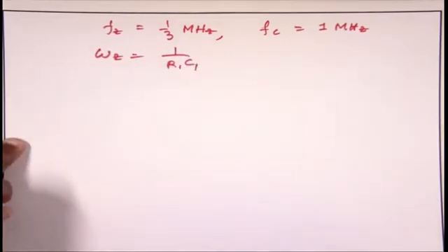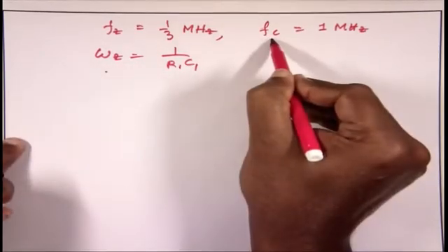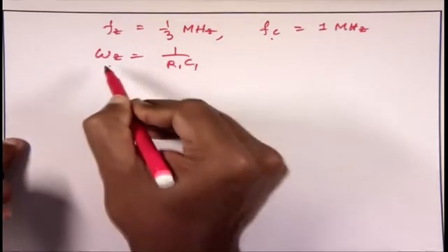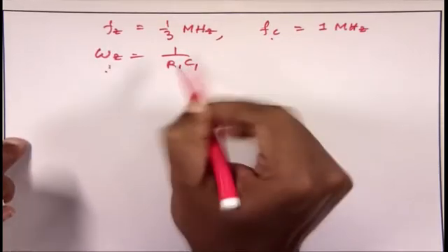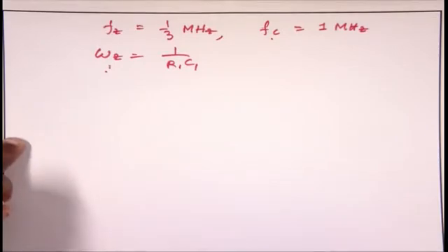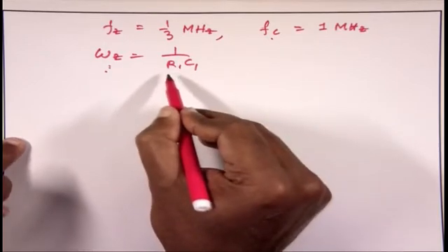So now you are coming to the actual closed loop filter characterization. From the locking time you know omega C, from there you got omega Z, and omega Z is nothing but 1 by R1 C1. From that you might have a clue to calculate R1 and C1, because the loop filter is the most strategic part, but you do not know R1 and C1 yet.